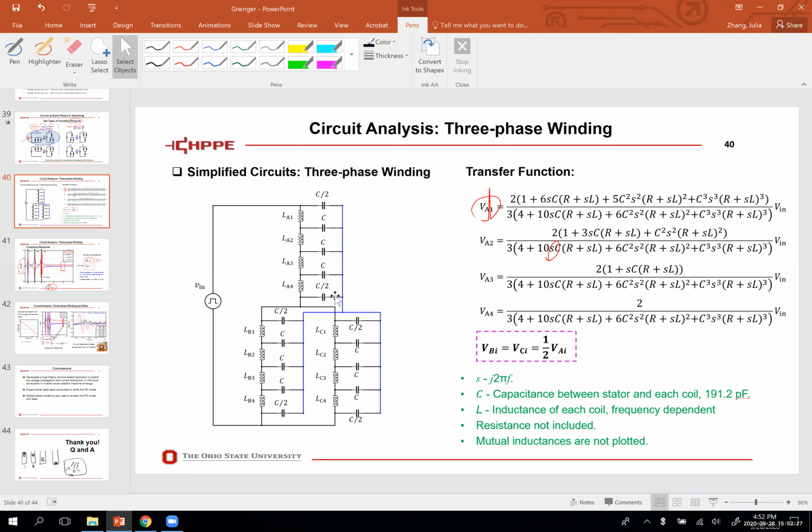Sure. In the automotive industry, the first thing they try to do is see, when we go to a higher voltage, or a higher switching frequency or higher dv/dt, whether the existing design is still okay, without excessive voltage stress. If it's okay, they wouldn't try to modify the entire design. But if they see from the simulation or analysis that the voltage stress gets close to the partial discharge inception voltage, then they will start to think about whether they need a big change to the current design.